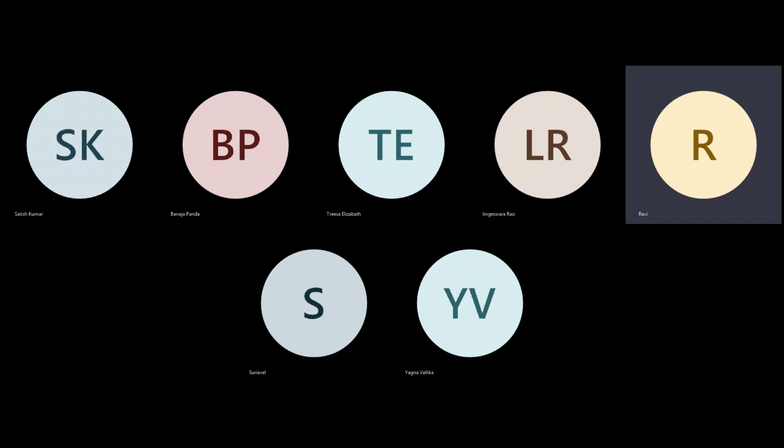If there are 50 output pins, 50 into 8, 400 nets will be there. Yeah, I am talking about 8 macros. So 400 nets have to be routed. And this particular route can happen where the cell is positioned, or if the cell is at the bottom, we are talking about the channel where the route has to happen and then connect to the cell sitting at the bottom. That means the 400 nets plus 50 nets, which may be common across. So a total of 450 nets have to be routed in the channel. Not like 100 into 8, 800.